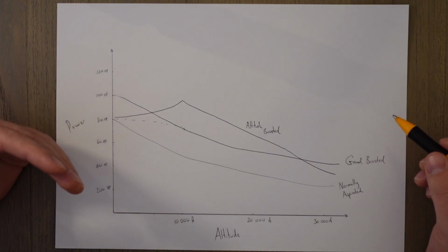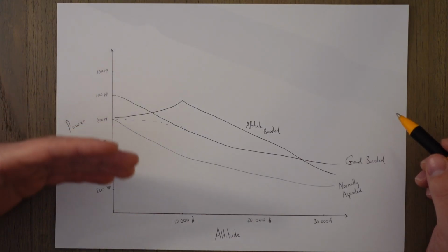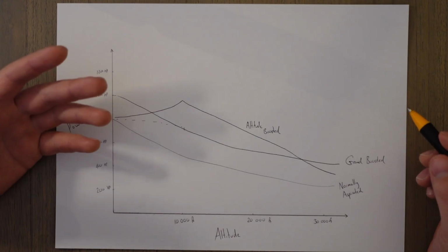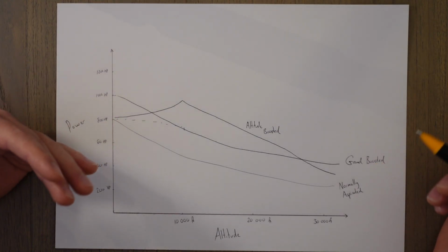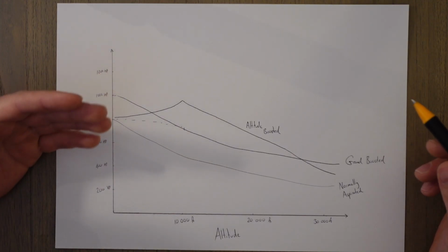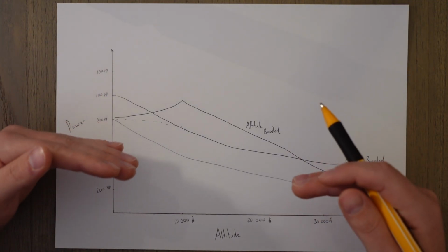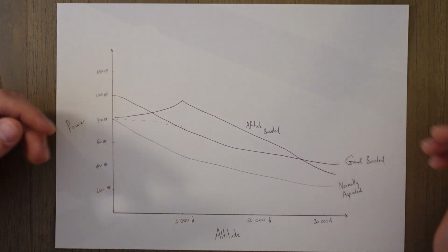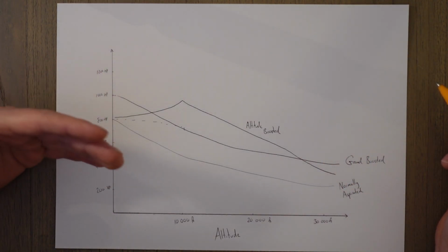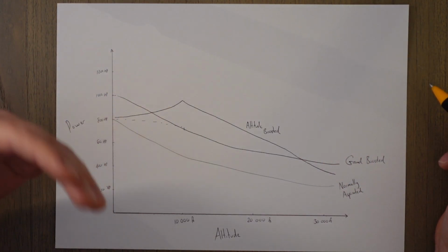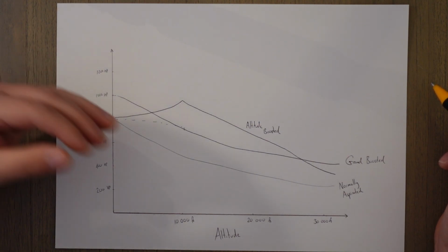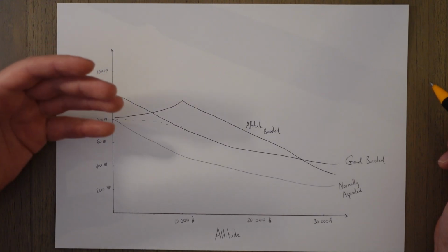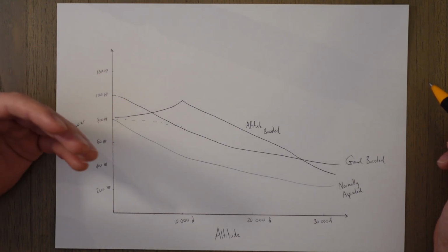The exhaust gas is hot and therefore the impeller gets hot, and this means that we can't compress the air and fuel together that we might do in a supercharger, because the compression might cause the temperature to rise too high and cause a combustion before the fuel has even entered the cylinder. So what we do is we simply compress the air on its own, then add the fuel in, and it gets basically the same effect.